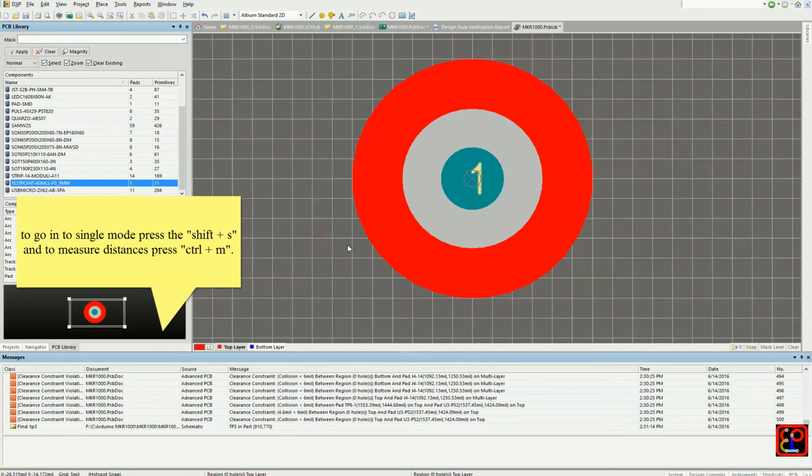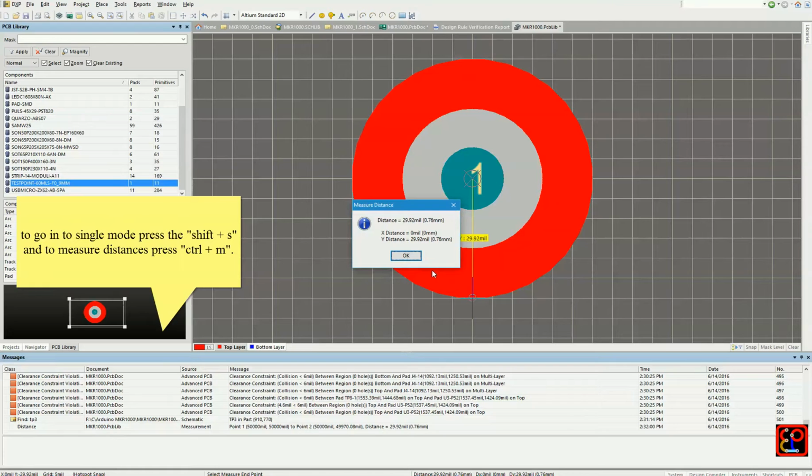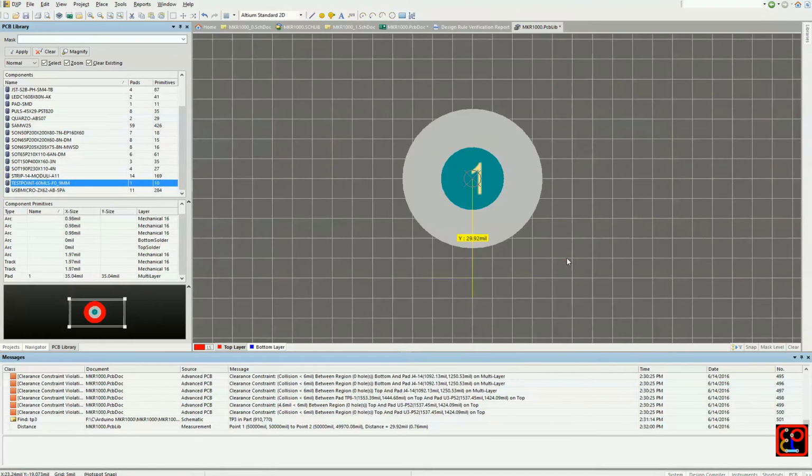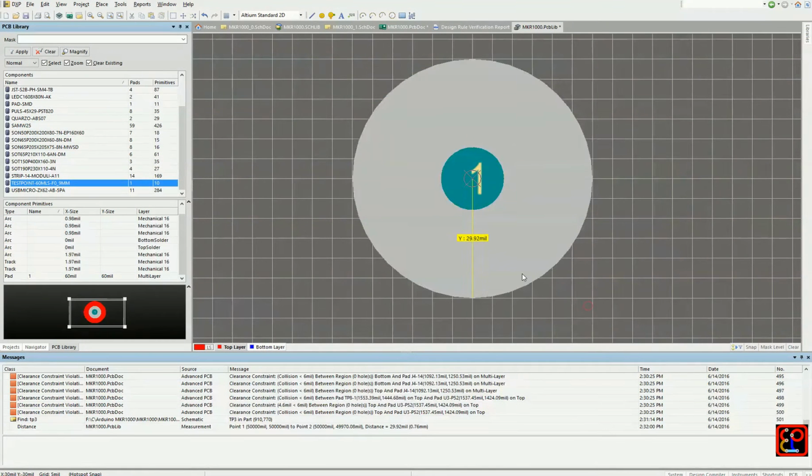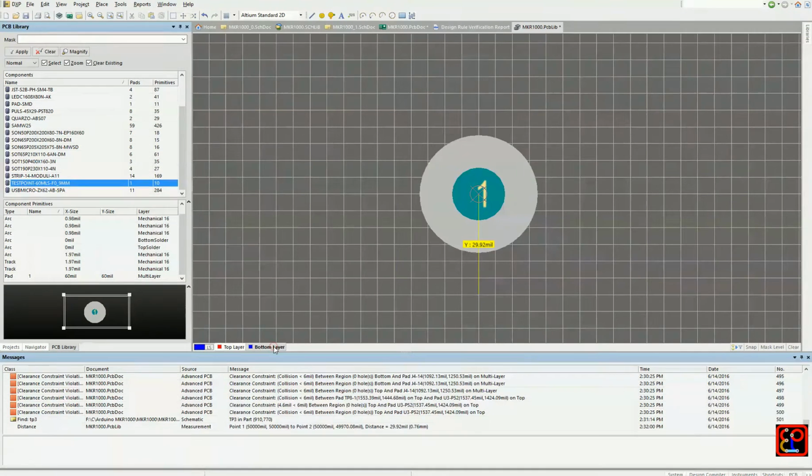On the top layer, there is a shape that is creating the error. In Altium, they call it a primitive. Just remove the shape, pick the size and shape of the pad, and modify the top layer to match the size of the shape that was there.